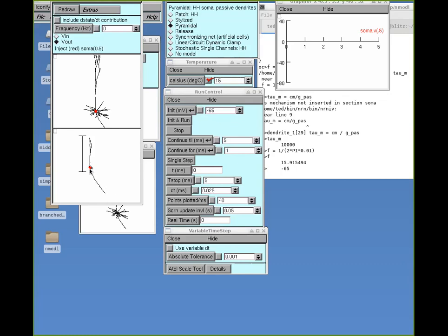Okay, so if I put in a millivolt here, the potential here will be approximately e to the minus 1 times a millivolt. If I have a millivolt signal there, the potential there will also be about e to the minus 1. Actually a little bit not quite as attenuated. And this is just at DC. And if we go up to higher frequencies, we see that attenuation will increase, and our cell will be redrawn with longer and longer branches.